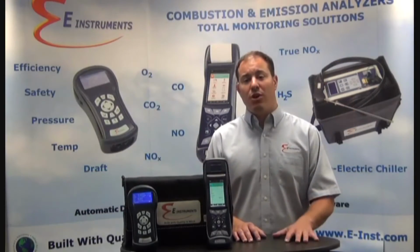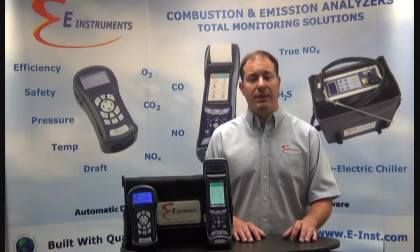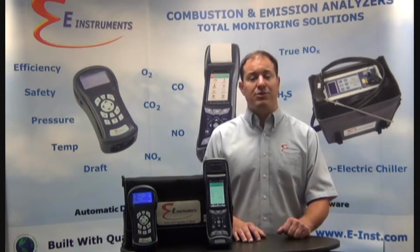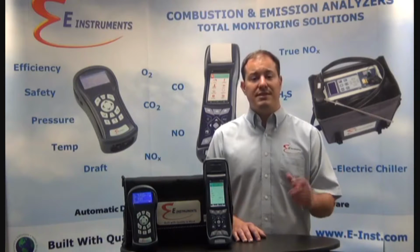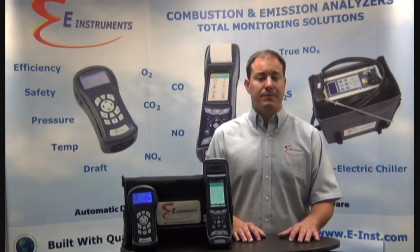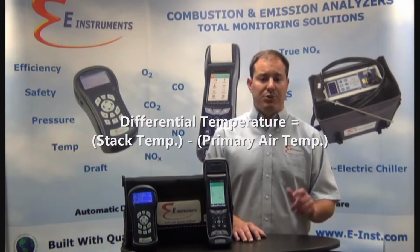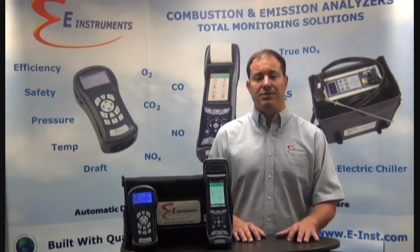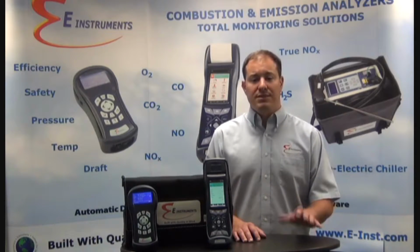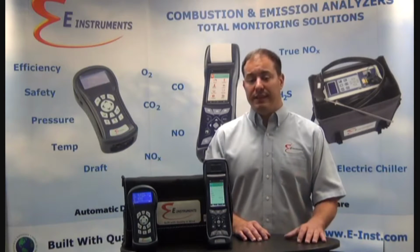For years, we were taught that all analyzers measure the ambient air temperature in the boiler room via a built-in internal temperature sensor, and the thermocouple at the probe tip measures the stack temperature in the flue. Then the analyzer calculates this differential temperature between the two, which is in turn used for the combustion efficiency calculations along with the O2, CO2 measurements, and the fuel type. However, things have changed lately.